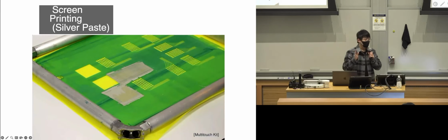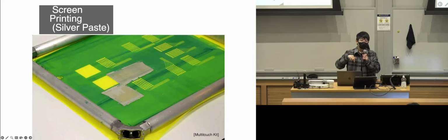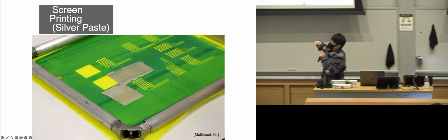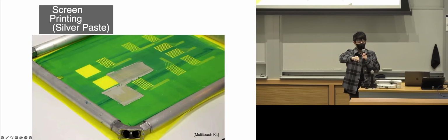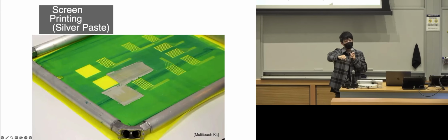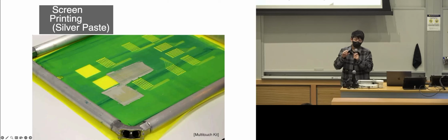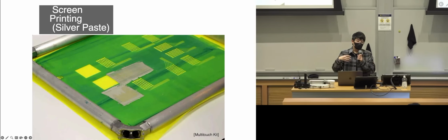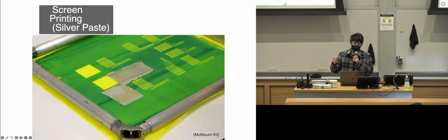I'm not sure if you guys know this term. If you order a PCB and you don't want to order the PCB assembly service, you usually order a stencil that has those little drawn out holes that can be matched exactly onto your PCB. So you have the conductive paste brushed over, so all the naked pads or footprints have just enough solder paste on it. So you can use an oven to bake the entire PCB instead of manually soldering one-to-one.